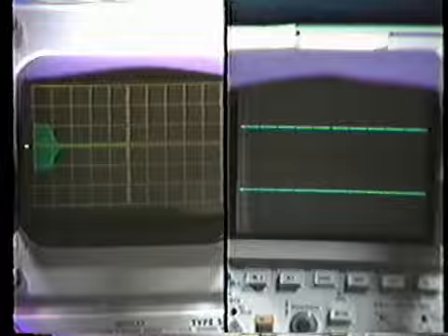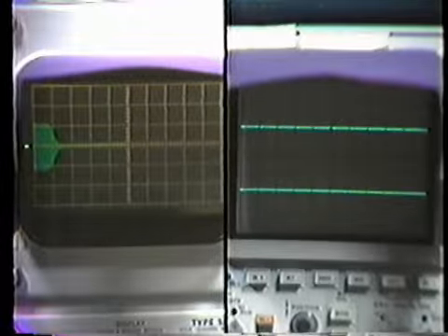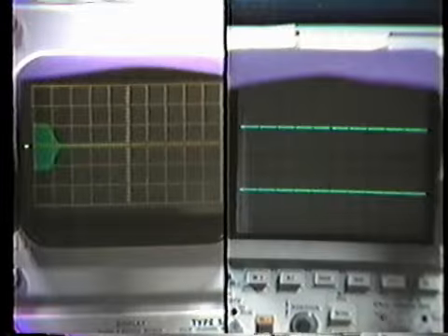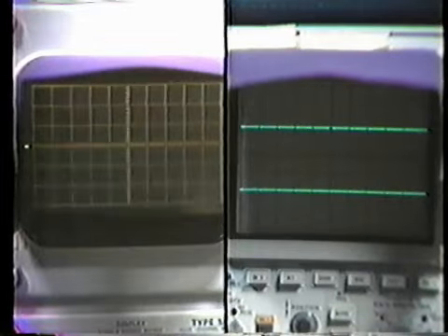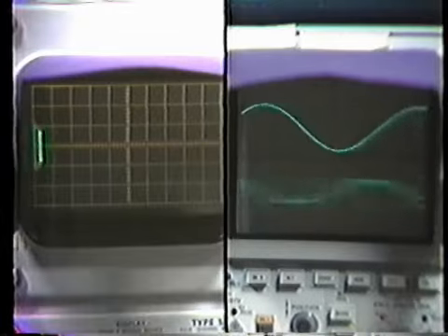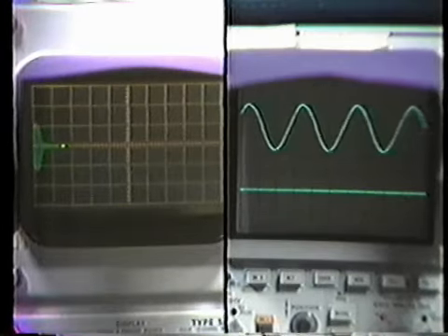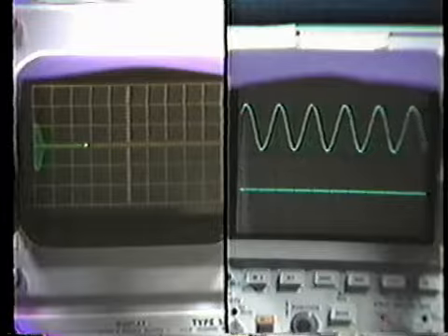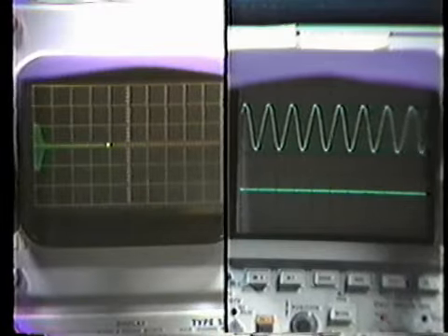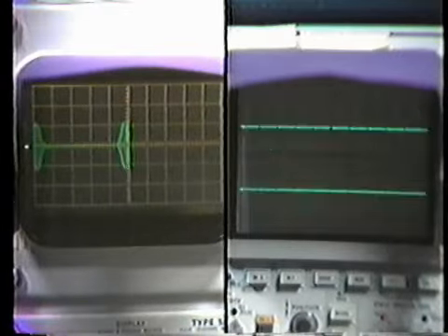We can cut the sampling frequency down to 10 kilohertz. And remember that the sweep range is 0 to 10 kilohertz. So now we'll be sweeping from 0 to 2 pi. So as we get close to 2 pi, we'll see the passband again.